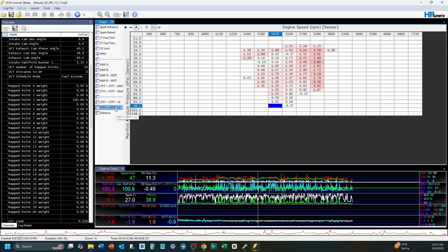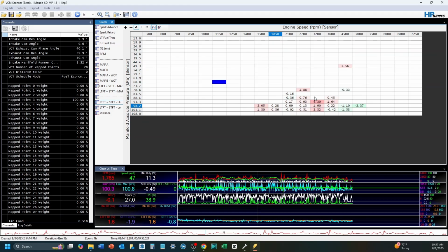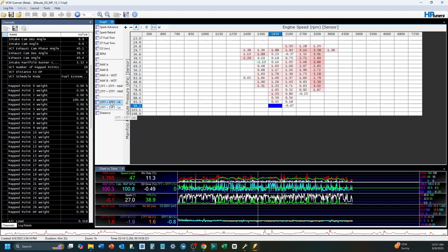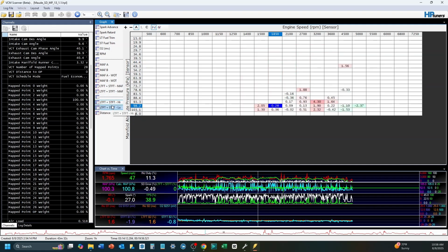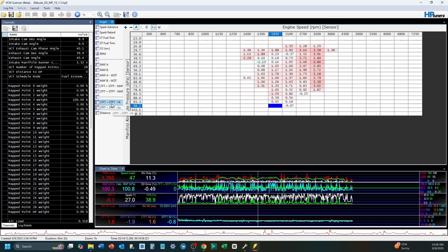And so likewise, that's the low state. If I go to high here, same song and dance, you're looking for trending. And here, I like this because, first of all, I'm not too far off, which is good news. This 4.3, that only happened 5 times, but yeah, I'll take it. This gives me a good picture of what was happening in the high state. And this is the other thing about this. These two tables together, you can see how they complement each other. It's one part of the range versus the other. If I was to have both of these in one table, that's a pretty good speed density VE adjustment.